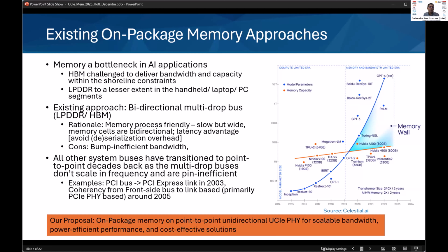Now, an alternative, a better approach in my opinion, would be to deliver very dense compute on the package. We strike the right balance there between compute, memory, and I/O. This is where UCIe can help, both in planar interconnects as well as vertical interconnects on the package. The challenge we are having with HBM is not on the HBM memory stack by itself, but in the interconnect between the SoC and the logic die. The SoC is shoreline constrained, so we just need to get higher bandwidth density.